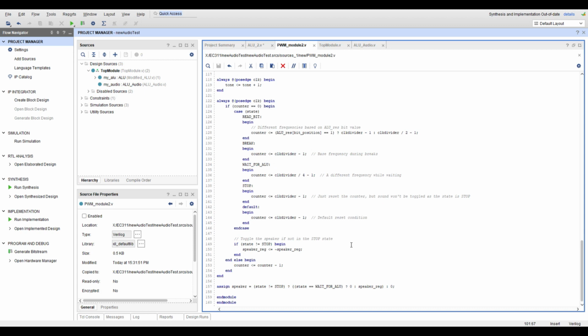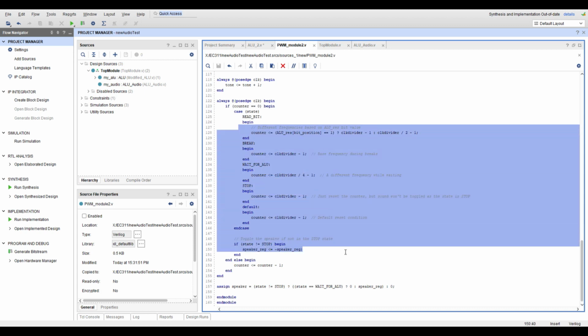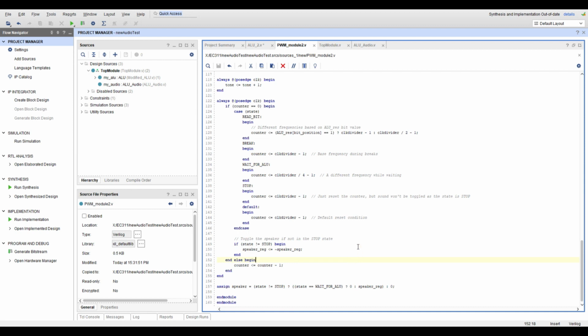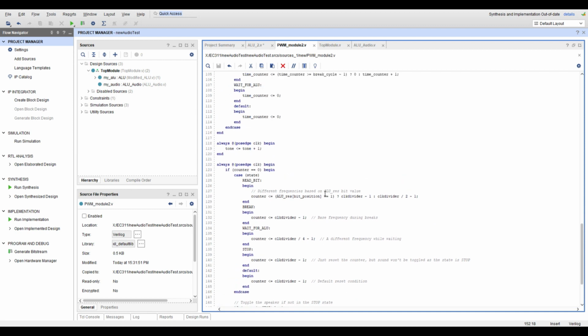However, we also encountered the challenge of achieving the correct combination of the ALU output, so we started to simplify our method. In our new approach, we decided to modify the output so it varies only in amplitude, controlled by the duty cycle using a set threshold. Jackson will further elaborate on our methodology.